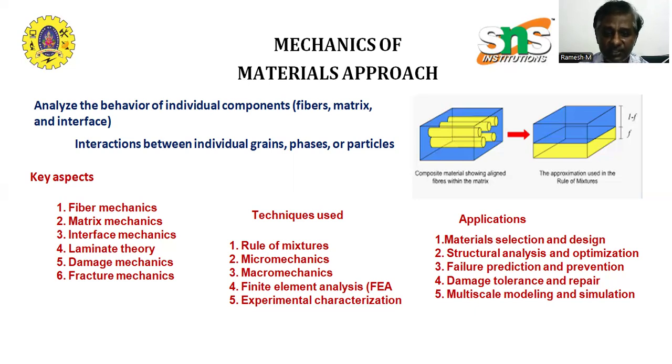Next, fracture mechanics. A very important chapter. It is also studied as a separate subject generally from the structures point of view. So here in fracture mechanics, the things generally concentrated on are fracture modes, fracture toughness, and fracture mechanics models. Here, mode 1, mode 2, mode 3, like opening, sliding, and tearing. These three are called fracture modes generally.